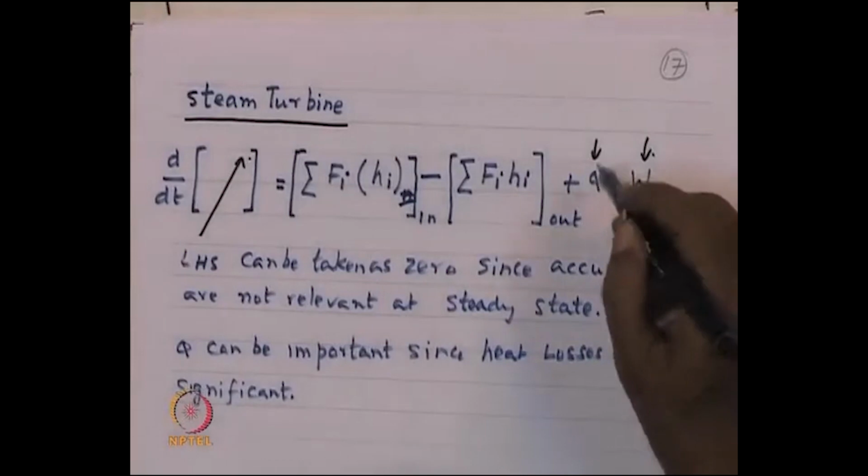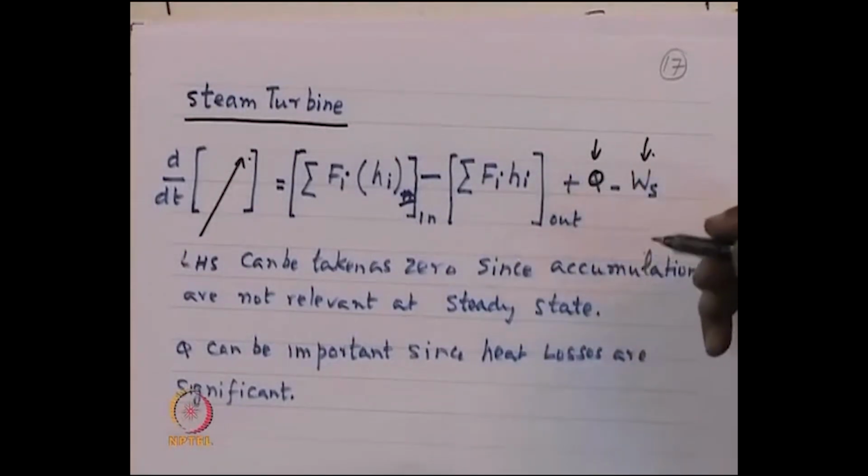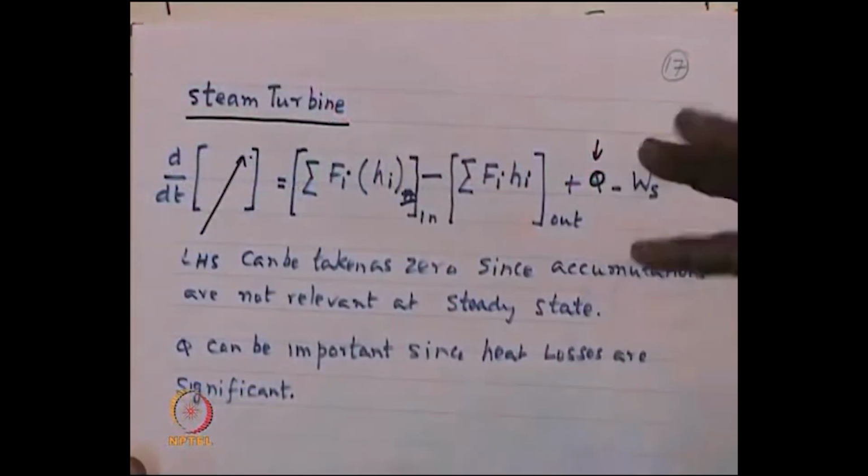Now, what might happen is that this Q is the amount of energy that we put in. We may be thinking that we are putting in 100 units of energy, but what actually goes in is only 30. This could happen to us. How do you overcome this? You overcome this by recognizing that this Q may not be a complete description of what is going on. Therefore, we must know all the heat pathways to understand where the problems are. So, what this equation explains to you is how we can interpret that information to understand our system appropriately.